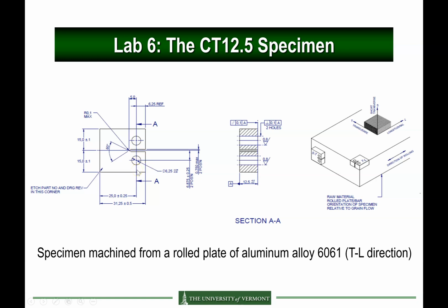And what is important here is the notch we form is at 5 millimeters precisely from the pin. So we're going to look at images. You'll be provided with images of the crack after propagation in fatigue before we perform the K1C test.